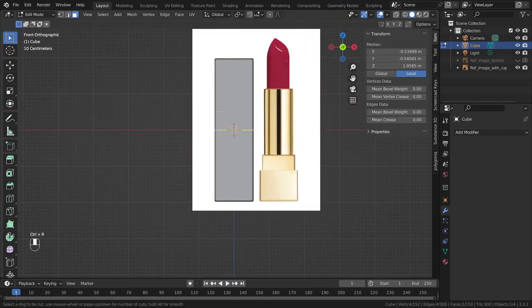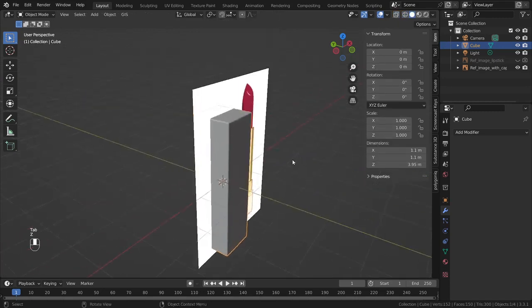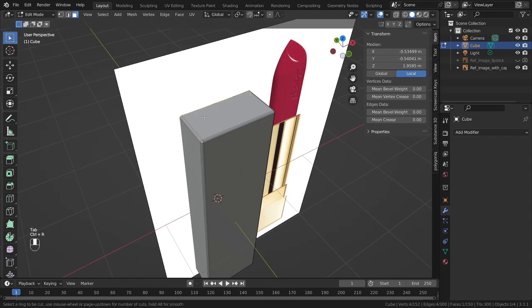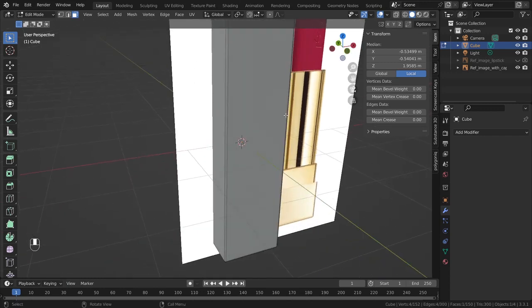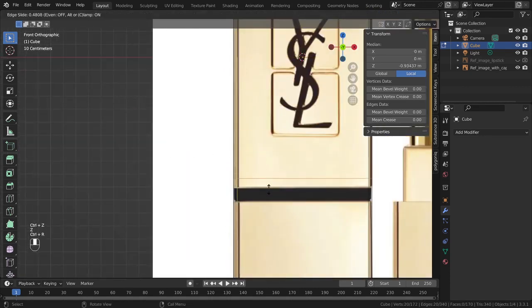edge loop with Ctrl R. As you can see, with Ctrl R, a yellow line comes up. And this line goes through the entirety of this model, which is also very nice with quads, because quads keep a nice flow in your model. But that aside, Ctrl R, then click, and you can still move this edge loop around. When you're happy with the position, you can left click and it will go there. Or if you want it to stay in the middle, you just click once and then right click and it will snap back into the middle. However, what we want is to have it here.